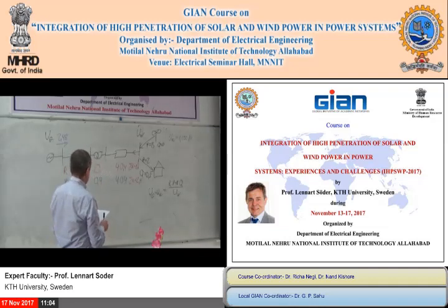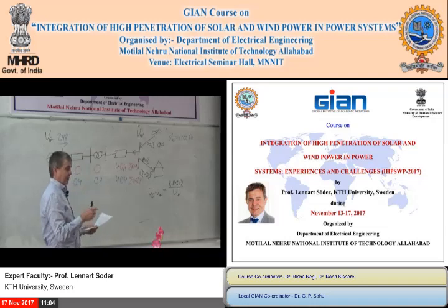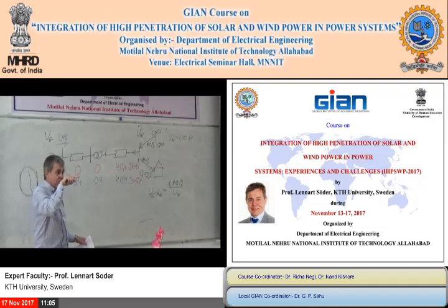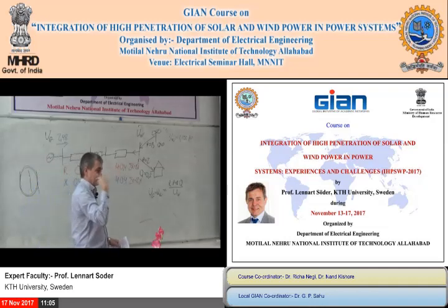When we change to cable, what is happening is that, in an overhead line, let's take the basics. In a transmission line, you have these 3 phases, and you have the current going around in a circle like this. And currents going around in circles, if it's AC currents, create an inductance. If you have a big circle, you create a big inductance. If you have a small circle, you create a small inductance, because it's the magnetic flux that is changing.